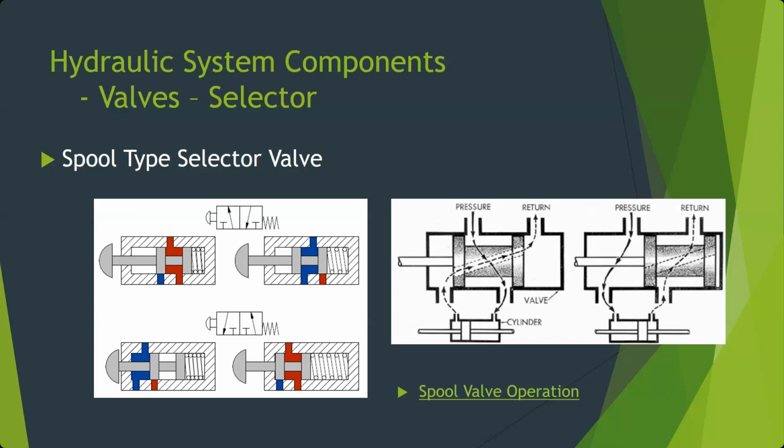You don't see them a ton in aviation, but they basically show what ports are, where fluid flow goes, or what ports are being capped off, that kind of thing. And so if you do industrial hydraulics, you'll see a lot of these diagrams right here. And then the little zigzag line at the end, these have springs.